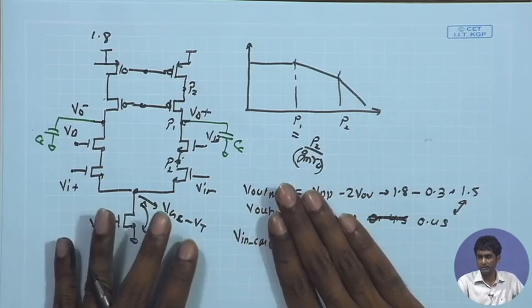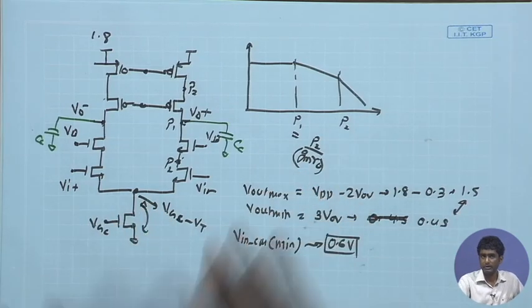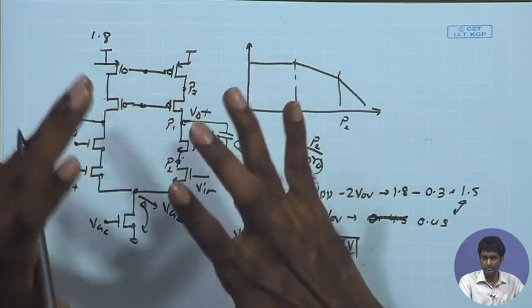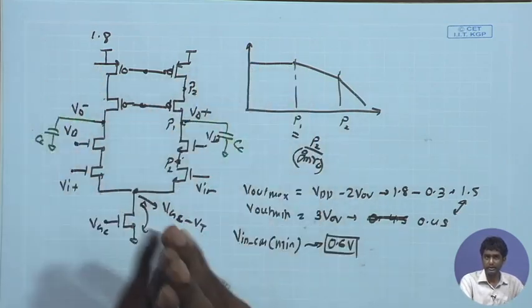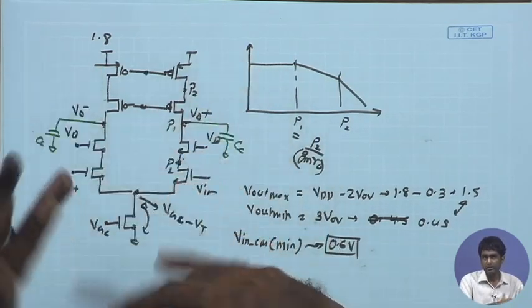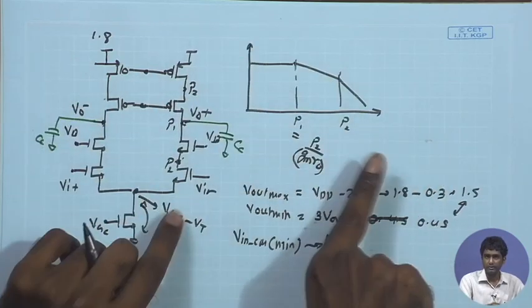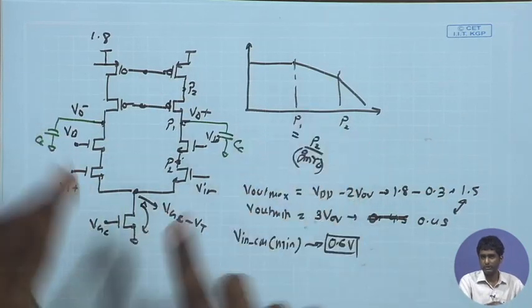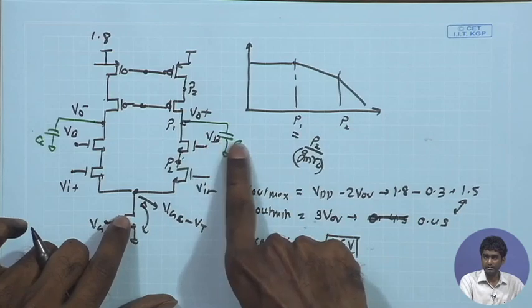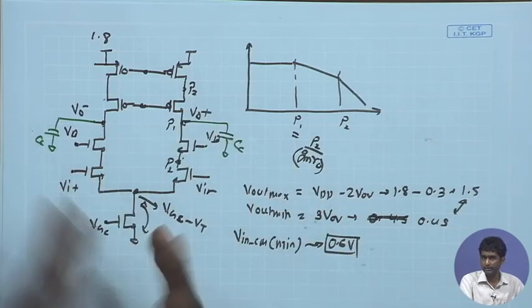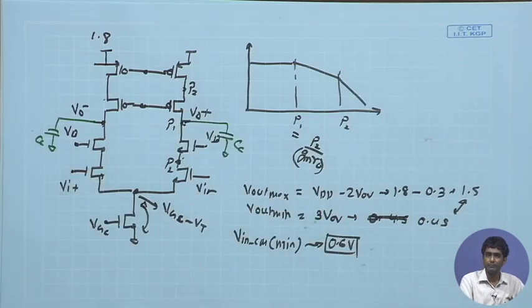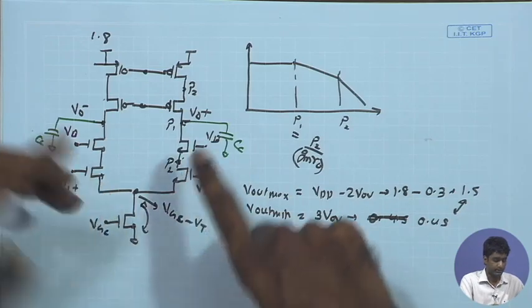This point is clear, what we are trying to mention over here. So, the good points with this scheme, with this particular circuit, is good differential gain. In a single stage you are getting gm ro square, a self compensation property, with the help of which, without even adding a very significant, very large capacitance, you are able to achieve a good phase margin, and we will see that.